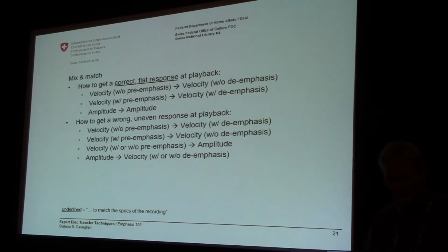Now, it is also possible, of course, to get a wrong, uneven response at playback, which brings us to the other examples. Velocity without pre-emphasis against velocity with pre-emphasis is wrong. The other way around is also wrong. Velocity with or without pre-emphasis read with an amplitude-sensitive device, such as an optical device, for example, is wrong. It's not wrong, it's simply not flat. And the other way around, same thing.